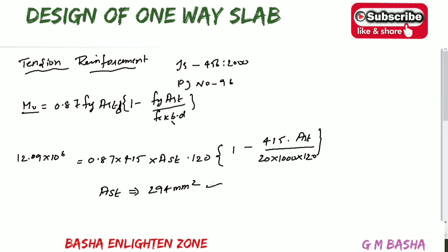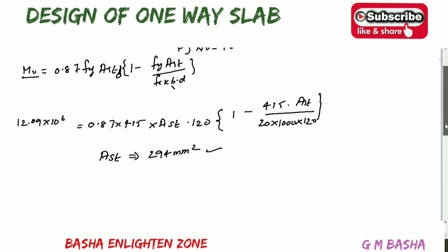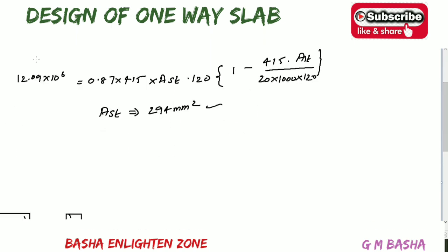And again, whatever the area of the steel you get here, you can check the condition whether it satisfies the minimum reinforcement or not. So for that purpose we are checking that value according to the Indian Standards. So that is minimum reinforcement. So what is the minimum reinforcement required in this slab?